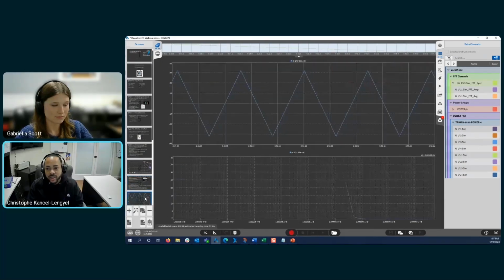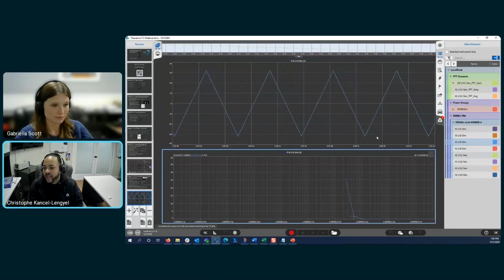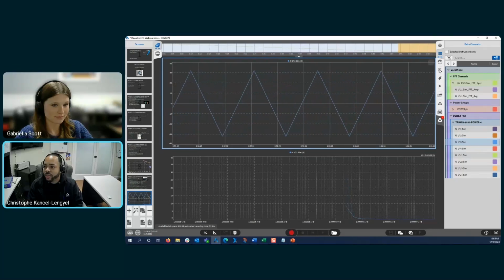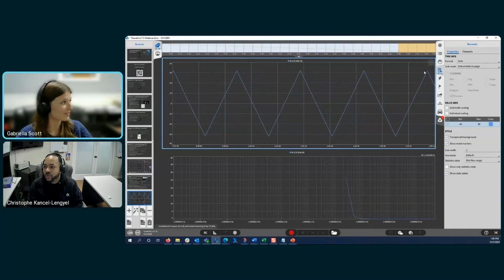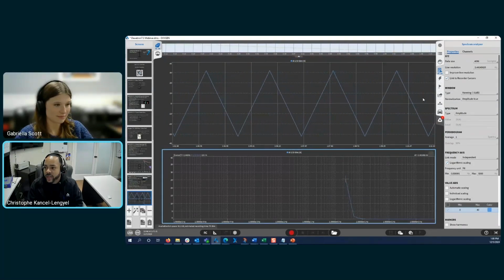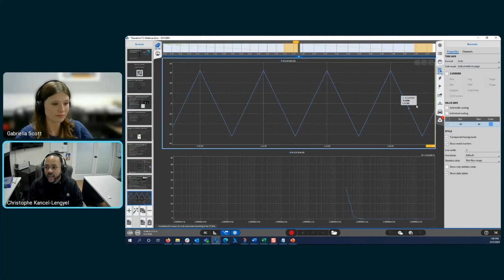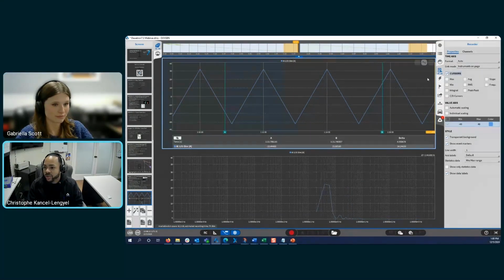So what this looks like is, for demonstration, we have our recorder up top and our spectrum analyzer on the bottom. If we head over to the instrument properties, the link mode for the recorder is going to be set to instruments on page. And the spectrum analyzer, we're going to link to recorder cursors. So once that's been done, we can go ahead and freeze since we're in live mode and enable our cursors for the recorder. And as you can see, in between points A and B, we'll be able to view the FFT between these.